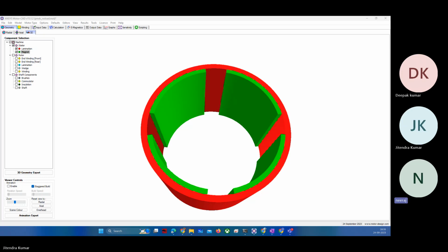Sir, then we have to take care of the temperature limit for this machine during operation. Yes, yes, yes. That's the main point. You can generate any kind of performance, but to maintain that performance, you should have a particular kind of cooling mechanism that will extract the heat out of your windings and the losses that will be generated during torque production. So we have to maintain temperature below a certain point.